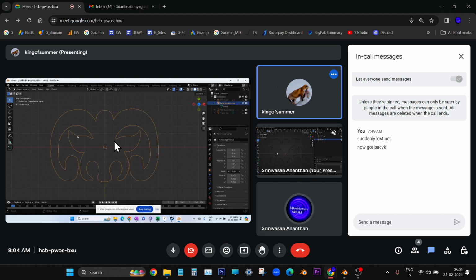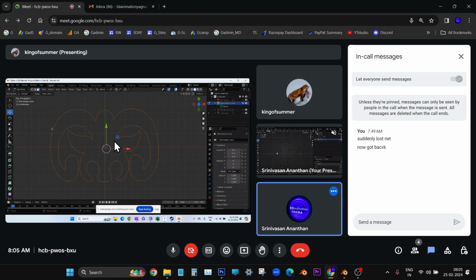Now you go into edit mode. Now it is showing only edges, they don't have faces actually, but because it is the nature of mesh, the face mode is still on, but there are no faces. Now press 1 on the keyboard to switch on the vertex mode. No, okay, you go to numpad 7. You go back to top view.